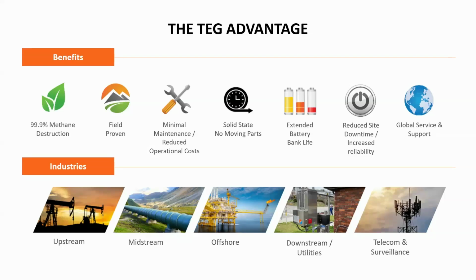And then it can be paired with batteries for battery backup or solar PV hybrid. And on top of being paired with those items, it extends the battery bank life as well. So when the TEG is running, it float charges the battery bank. You don't see the batteries discharge as often, and they last a lot longer. So rather than having to replace them every 2 to 4 years, you're getting batteries that last 5 to 10 years, much longer than typical. All this adds up to reduced site downtime and increased reliability, which is why they're used